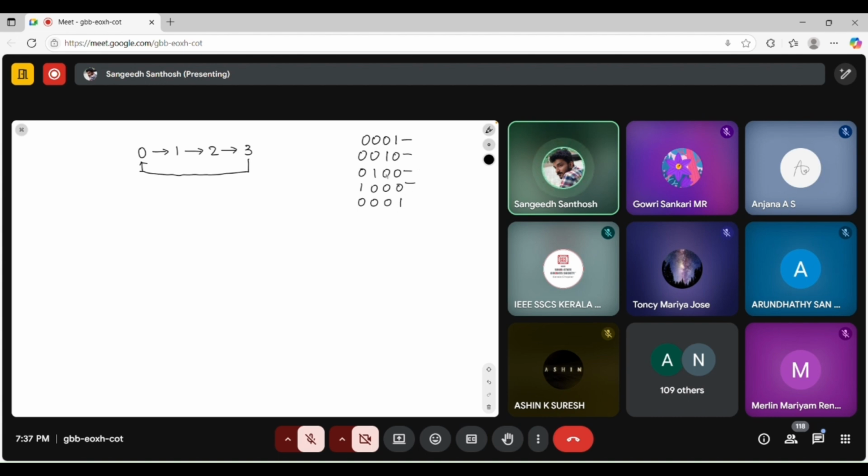So this kind of counter I want to design. So we will be using a rotate kind of operation here. We are rotating this, shifting these bits and giving this 0 to here. Understood? So a similar kind of thing we can do in Verilog.